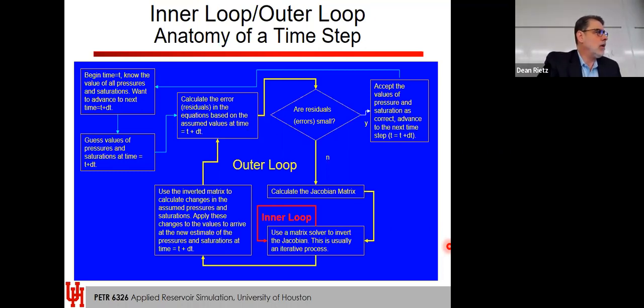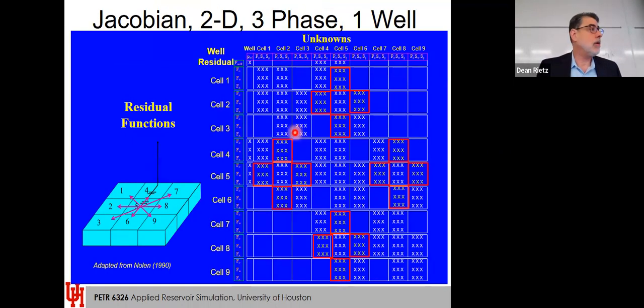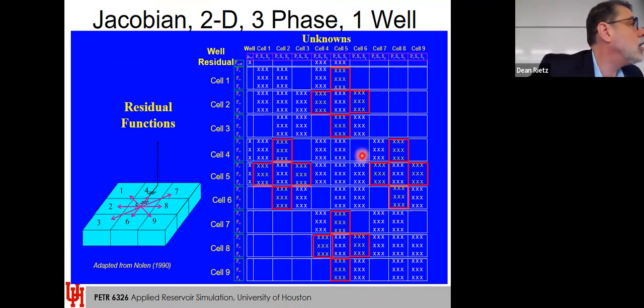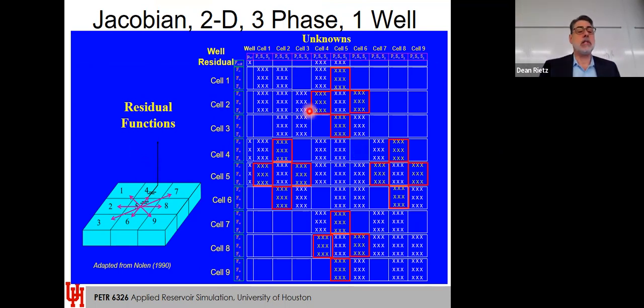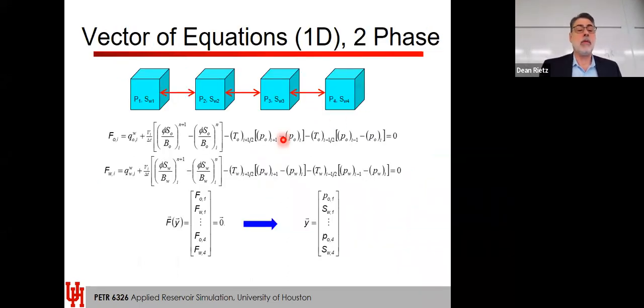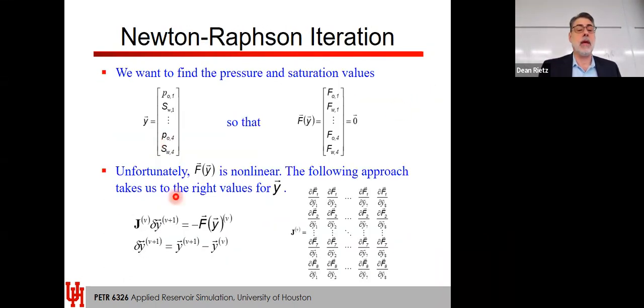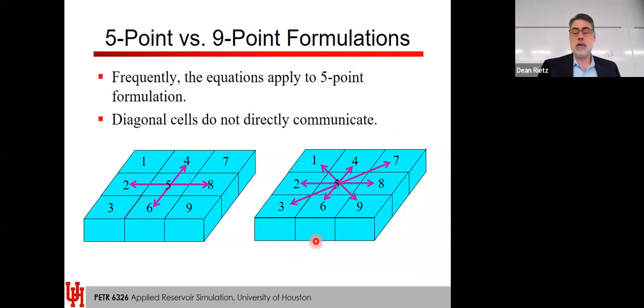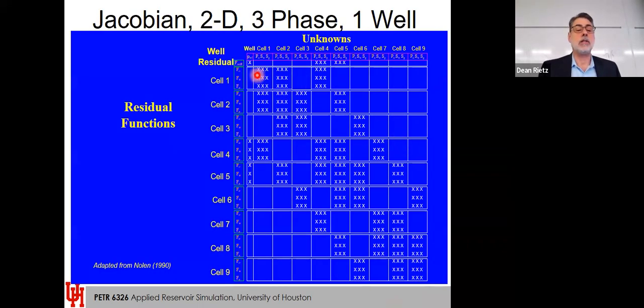For this phase, 2D, this phase. It's for all. We set up the equations. It's these equations. A phase block, Darcy's law? Yeah, so that's built into these equations. Remember, we set these equations up back here. This has Darcy's law and material balance. These are the equations that formulate the error function that we end up with in the Jacobian. These are the equations, each equation in each grid block, 3 equations for each grid block for the 3 phases.